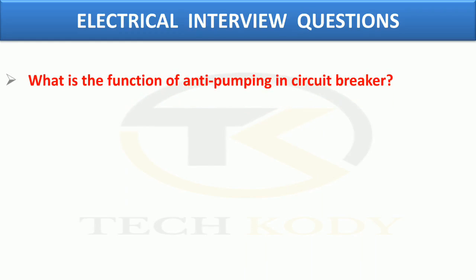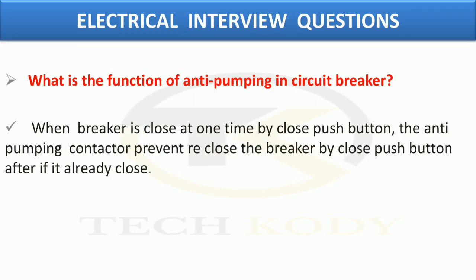The next question, what is the function of anti-pumping in a circuit breaker? When the breaker is closed once by the close push button, the anti-pumping contact prevents the breaker from reclosing by pressing the close push button again while it is still ready to close.